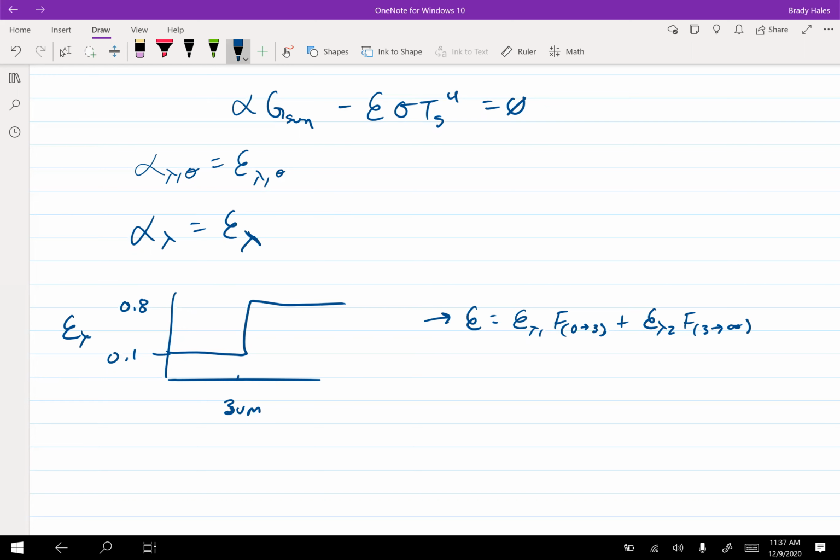And now here you might ask yourself, oh, but in order to calculate the fractional function, I need to know the temperature of the rocket, but I'm solving for the temperature of the rocket. So in this case, you would have to do some sort of numerical solution until it converges. So pick a temperature and guess, right? I don't know, choose 300K, just guess whatever. Make a reasonable guess.